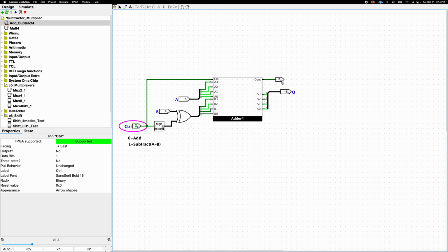All right, now this C out is a little interesting as well. For example, it could represent multiple things depending on how we're representing it, what we want from our output. So for example, if it was unsigned binary, it could represent the carry out to become the most significant bit. It could also act like a bit extender.